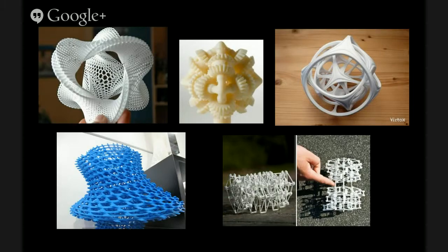And this is something that 3D printing is really great at: complex forms with internal structures. It's super hard to make that kind of stuff any other way. You can't CNC mill this, right? You can't cast this kind of object in any sensible fashion. But for a printer, it's not necessarily any harder to print this thing than it is to print a solid cube that size. In some cases, it's a lot easier. That's the buzz for 3D printing, that there's no cost for complexity.